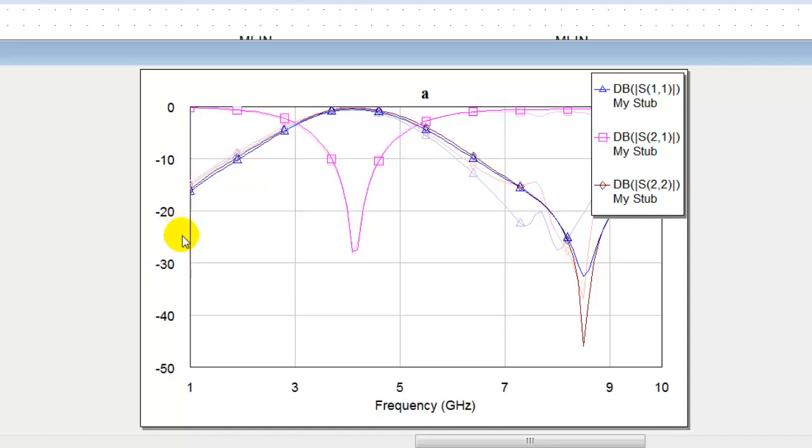And you can see the differences here, and in particular, when we look at the S11 up in this range where my cursor is, you can see there is quite a difference. What's the difference from? Well, we had that ground plate, and also perhaps some of the models aren't as accurate as they maybe should be, because after all, those were pretty wide lines for the T, etc.